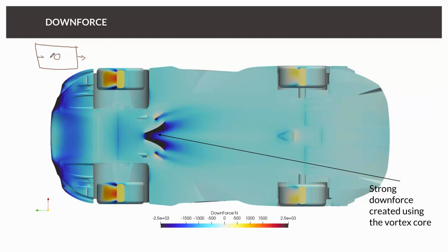Closed in this case means that there should be no hole on the geometry of our sphere. But if it's open, what will happen is that the flow streams in, but it cannot leave. But what you can also do is, instead of a sphere, simulate something like this. The sphere has an opening, but the model itself is still closed because we have this inner wall. So whenever you want, for example, to do a simulation with internal flows, which is also possible, then you need to make sure that your internal channels are also closed. But then it's absolutely fine.